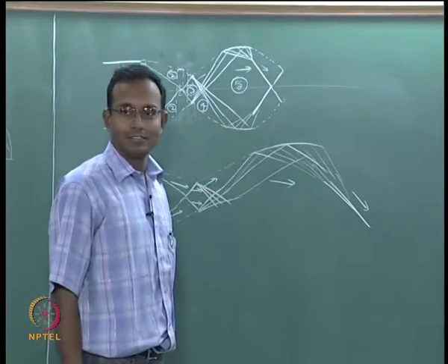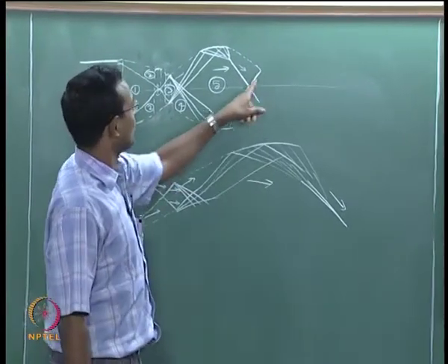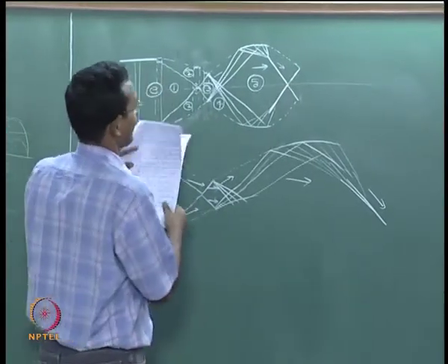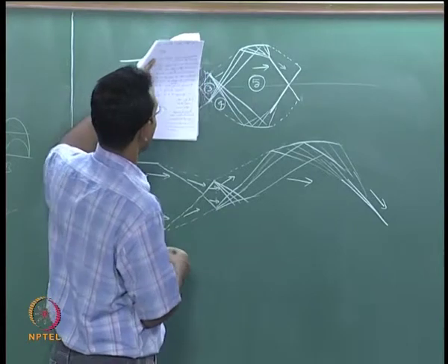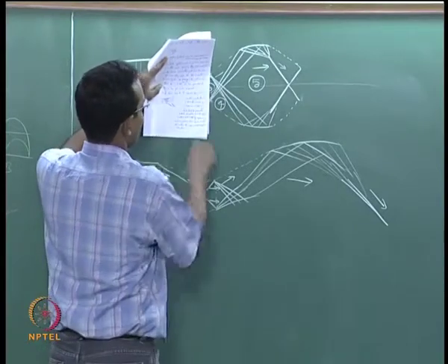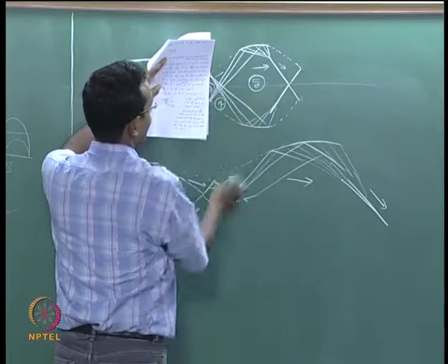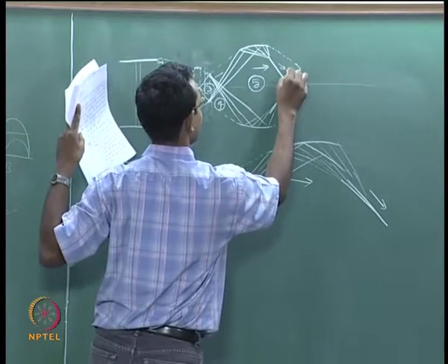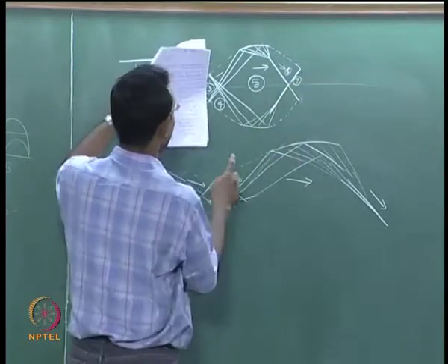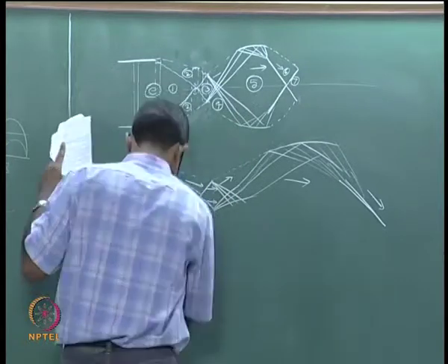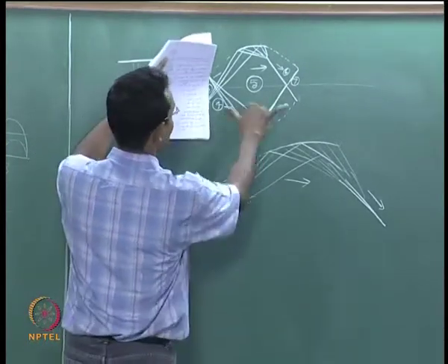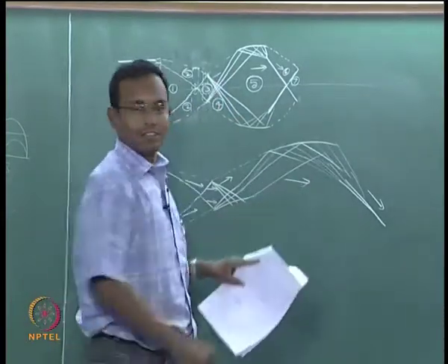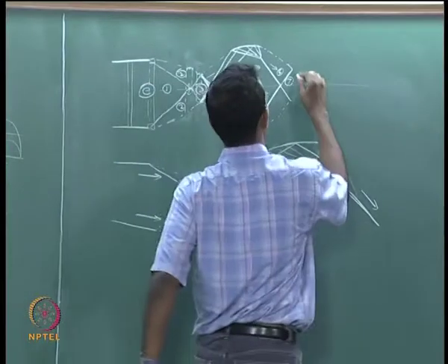After this, what should happen? Shock goes and hits a boundary, expansion should start. If I look at it, that same thing happened here. Shock went and hit the boundary and immediately expansion started. So, what happens is this whole sequence from 3 to, I did not mark this region, this is 6 and this is 7, 3 to 7, the whole thing, that whole region I am going to capture and paste it again there, take and paste the whole thing there. So, I will have that whole cell forming here.